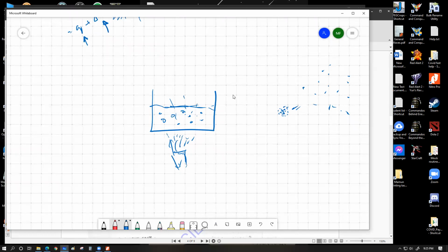The next thing is that, try to visualize this. When the boiling was not happening, this part was entirely filled up with atmosphere. Let's say I'm showing the atmosphere with green. When the boiling happens, the water molecules are going to come over here in gas state. They have to push out the atmosphere and make their own space, because that's the gaseous state that you just produced out of water. So they will have to occupy their own volume, and to do that, they have to push out the atmosphere out of their path. There is pushing. Pushing means work is done.